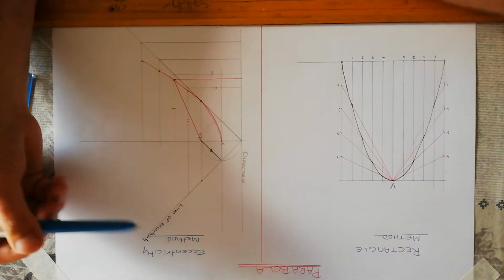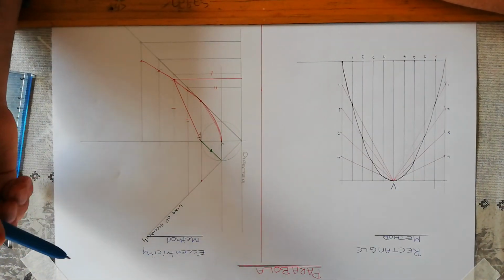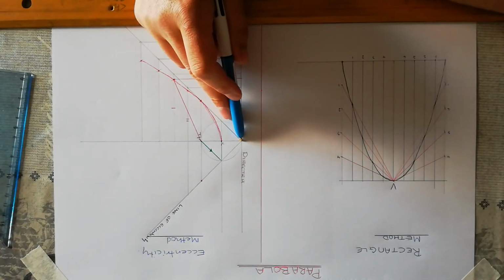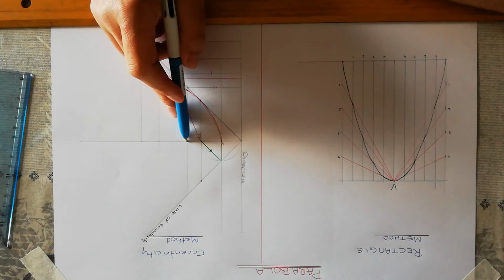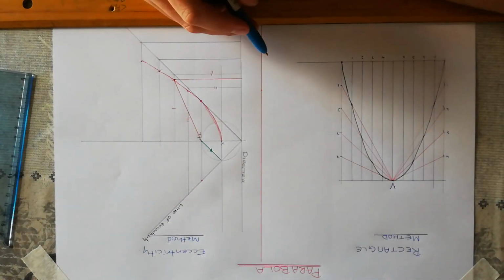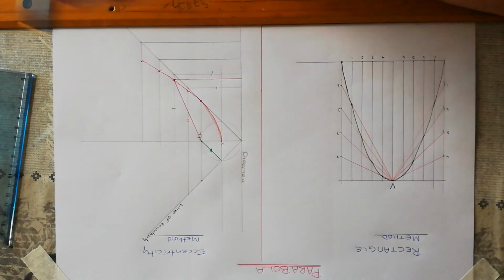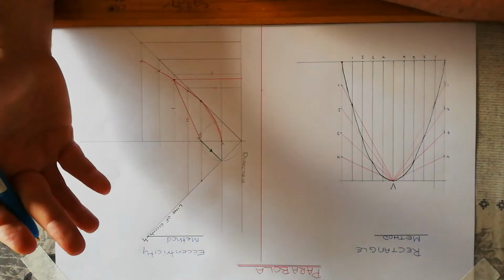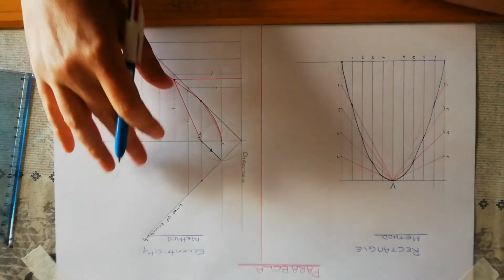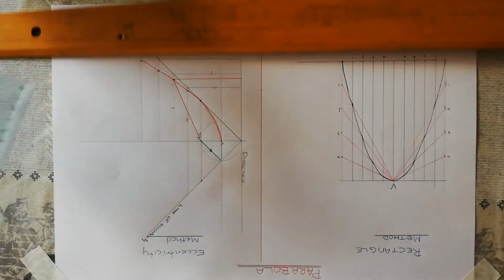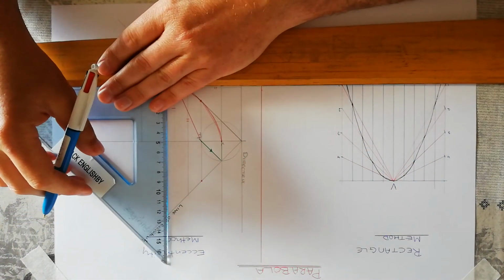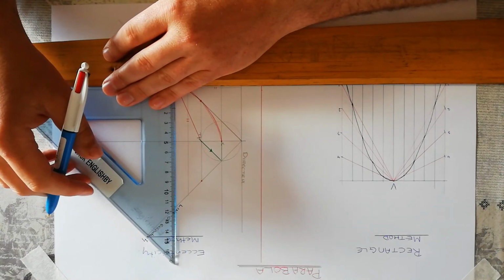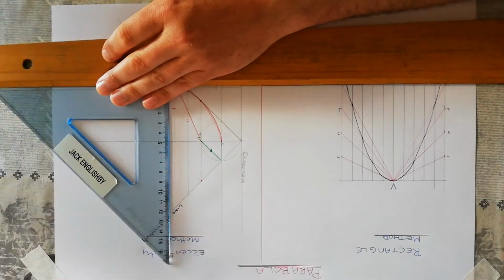Now, the eccentricity method and the compass method would be very similar. So if you had the focus and you had the vertex and the directrix, you could just measure from the directrix out to any point and swing it from the compass till it hits the same point. It's the same system that actually applies, you just don't need the line of eccentricity. But it's the exact same procedure. So if I decided to do the compass method and I didn't have the line of eccentricity, I could draw any line up here. So I'm going to draw a random line.